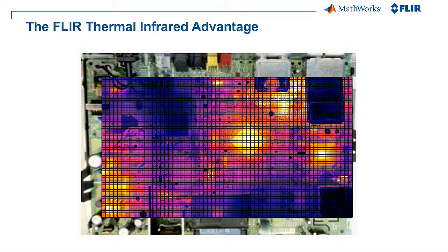Yeah, so it's essentially like having, looks like thousands here of little thermocouples at each pixel level. That's exactly right. Yeah, but whenever you introduce a thermocouple, just by connecting it, it actually changes the thermal characteristics. So this is totally non-intrusive without even affecting the actual material itself. No, that's an excellent point, Andy. This is a non-contact measurement methodology.